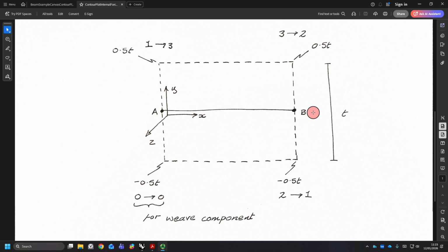But in order to do that, I want to generate a series of quadrilaterals that are essentially representing the profile of each element. So in this case, it's a rectangular element, so the depth or the thickness is the dimension that I'm interested in. And I'm going to generate a series of points, and then I just need to reorder those points so that they're always in a consistent order that's compatible with completing that quadrilateral mesh within Grasshopper.